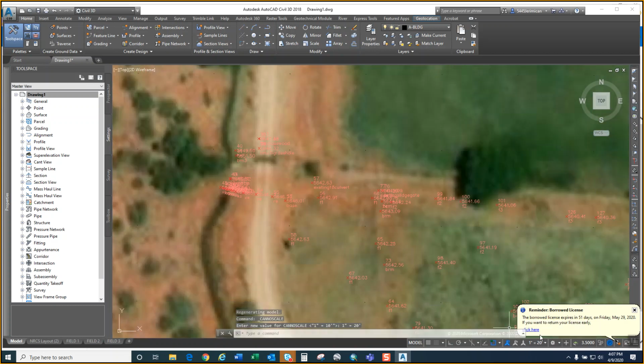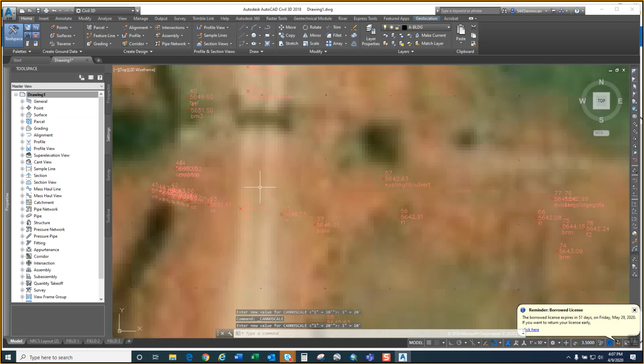Now I try to make it small or usable, because I'm killing two birds with one stone: we're doing a layout for a design, and this is also a training video. I'm going to do the layout from beginning to end. The command to do a line is PL for polyline.